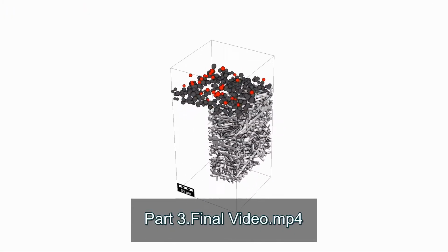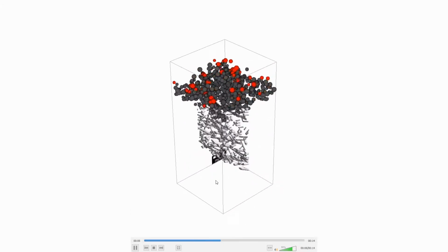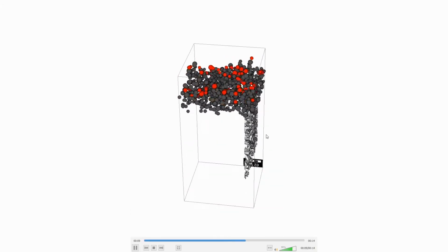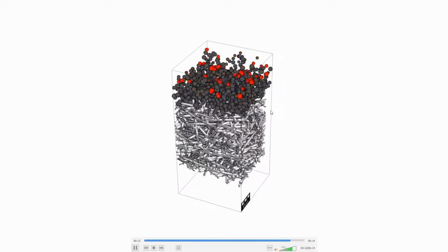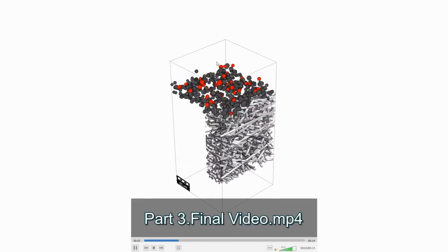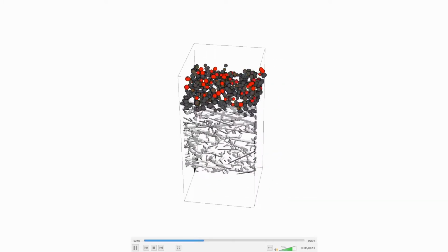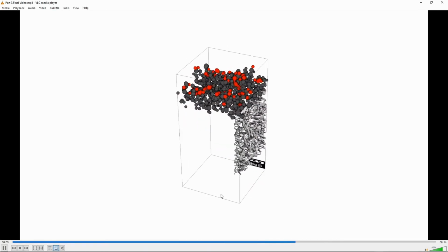We see our filter media rotating around its z-axis as it is cut in the x direction. During this process, the particle deposition is also animated. What we need now are the parameters for the rotation around the z-axis and the playback of the particles. The clipping is already done by our preset. We first add the rotation around the z-axis.